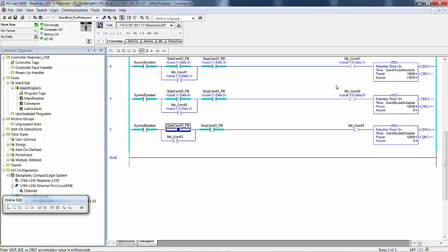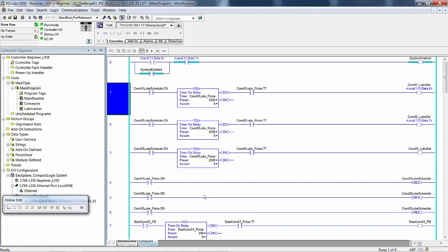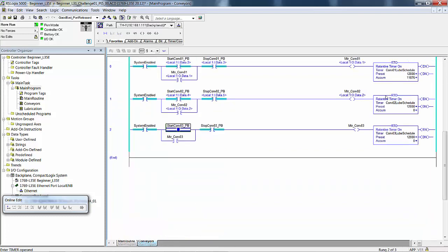I'm going to hit the reset button, which I think is 2. Yeah, we'll go back to main routine. Oh, that was in the previous lab. So they would have to be done. This is more data table carnage. You see, these rungs aren't true. Those bits aren't done. So we go look in Conveyors at this. It's not done, and we have no way to reset it unless I'm going to click there and type in 0. We carried over that number when we copied and pasted rungs from one routine to the other. So back where we were at.